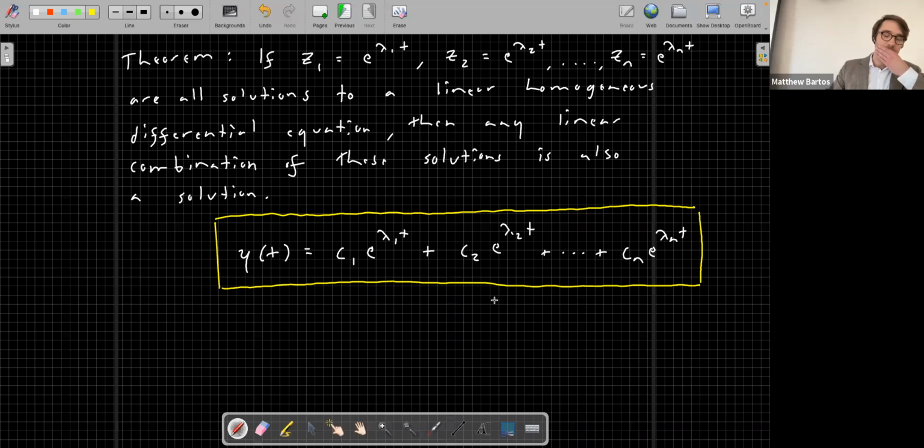Okay, so for a real world physical system, we know that there is a unique solution corresponding to that system's response, right? If you take our structural system and you disturb it at the first time step, and you simulate the homogeneous response, it'll always give you the same response. It's not like it's randomly picking different solutions. So how do we determine the values of these coefficients? How do we constrain our solution so that it corresponds to the real world physical behavior?